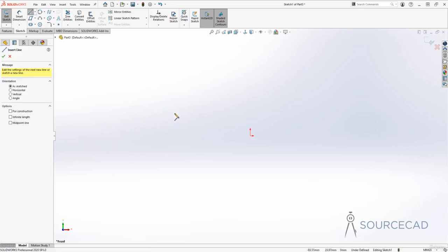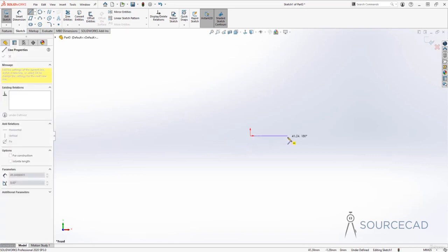And this time I'll make a closed loop with line tool. So I'll start with this origin point and I'll make a horizontal line. Now before I do that, I want to draw your attention to these things. So here when I'm moving my cursor, you can see that this value is changing, and that's actually the length, and it's actually showing the length in the current unit, which is millimeter. So right now it is approximately 48, then 55, 59, 60 and 61 and so on. So as I'm moving it towards right, it's changing that value. So you can approximately see the length and make your line.